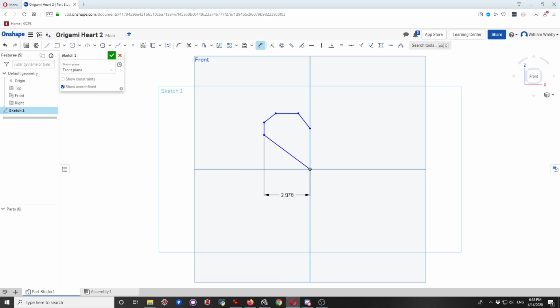So I'm going to start by choosing the horizontal width of this. And you can see my units are centimeters, because up here I had changed my default units to centimeters. Let's call it, I don't know, 3 centimeters wide. Why not? And then again, I want to choose my height for this. So I'm going to choose to dimension between that point and this point again. And let's make that also 3 centimeters.